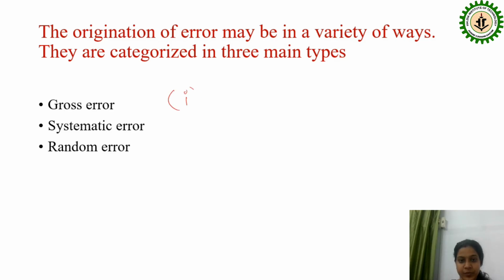First one is the position of the pointer. When the switch is off, for any kind of indicating instrument, the position of the pointer should be at 0. And when the switch is on and this ammeter is connected in series with the resistance or with the inductor, the pointer will start to move from its 0 up to a maximum value according to the unknown quantity.